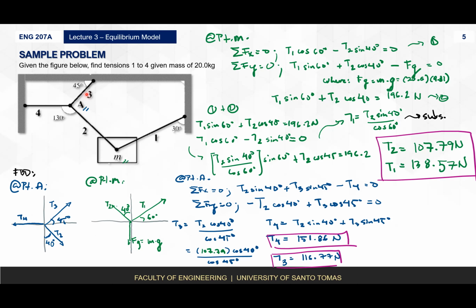With tension 3 naman, it's being pulled at 45 degrees. Using yung transversal rule, so this 45 degrees here, pag in-extend natin to, it should be 45 degrees rin on an XY axis, right? So there we go, T3. And then here comes T2. Now, paano ko nalaman yan? Well, if you extend again yung Y-axis mo here, and yung buong to is yung obtuse 130 degrees, you would create a 90 dito. And you're left with this particular angle. All you have to do is just subtract 130 with 90. You got 40. And hence, you got yung angle of inclination ni T2. So far, so good doon.